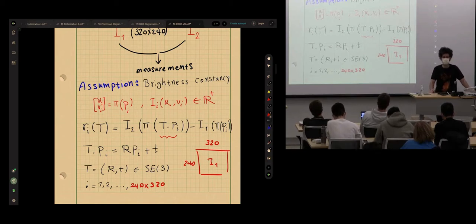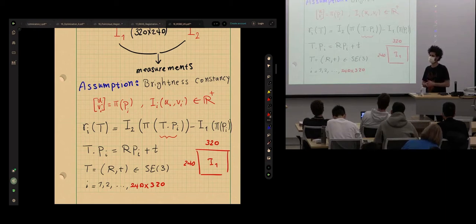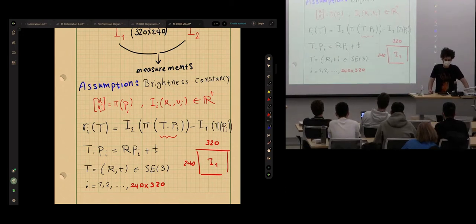First of all, the rigid body transformation has a constraint because R transpose R must be identity. That makes the problem constrained. Now, when we do it on Lie group, we do a trick using that exponential map to integrate. We ignore the constraint. But that gives us a local solution.